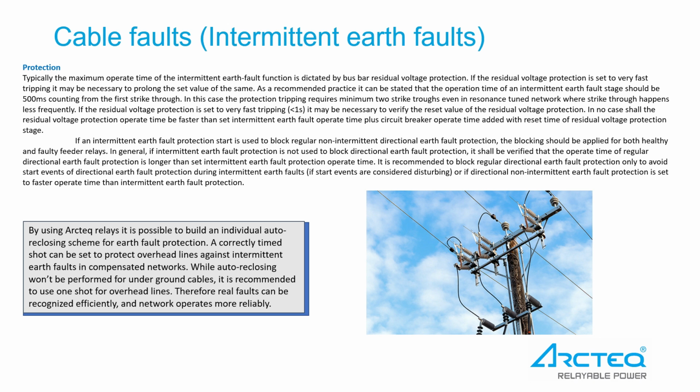If an intermittent earth fault protection start is used to block regular non-intermittent directional earth fault protection, the blocking should be applied for both healthy and faulty feeder relays.